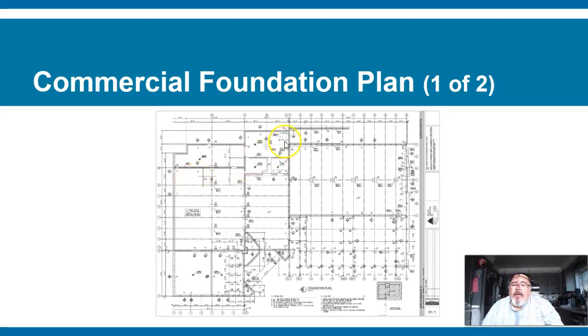So if there's pilasters, we measure and count the pilasters. And if there's a footing of a particular shape and a particular height, then we determine that footing. And if it changes in height, then it's going to have a new unit, because every footing is going to have more material in it. So you keep separate measurements for the different types of footings.